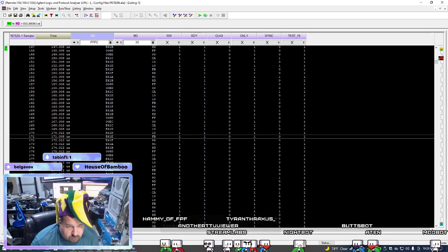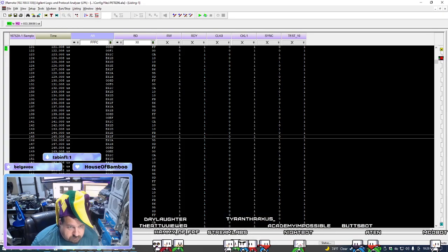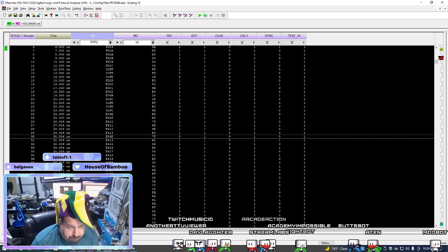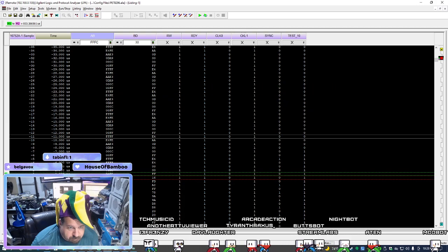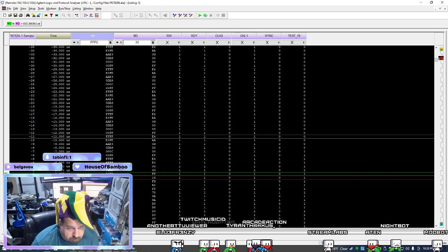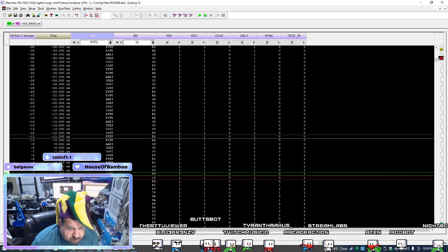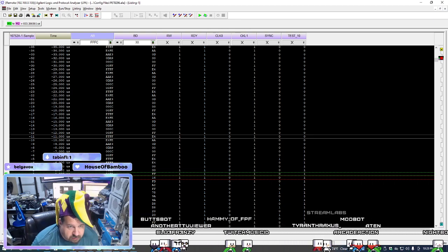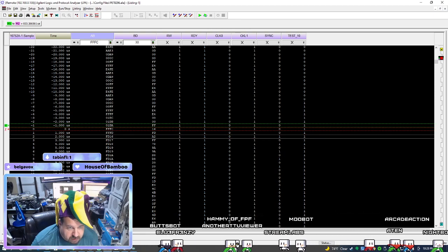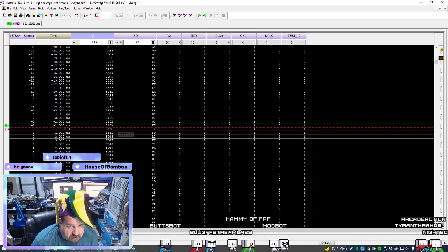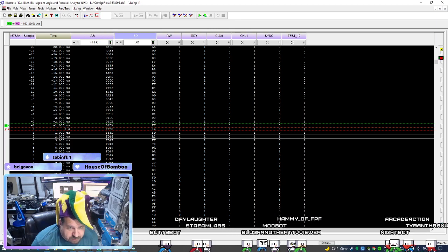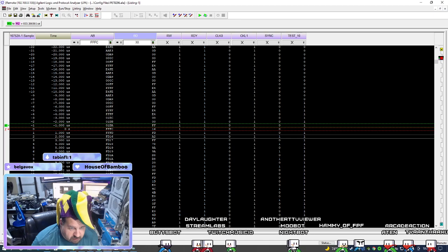Let's go back to Logic Analyzer View. Alright, so you can see the IRQ gets called a couple times. You can see the IRQ code being run up there. So here is the reset vector. FFFC jumps to FD16, FD16, 18, 19, 1B, FC.